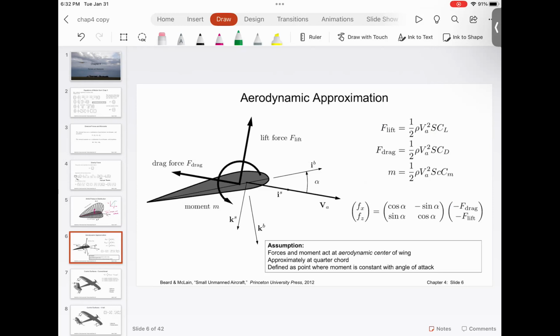So again, if you use a computational dynamics tool, a CFD tool, you can actually find out the pressure distribution and you can find the force. But for calculations, what we assume is that the resultant of total lift is acting at the quarter chord length.